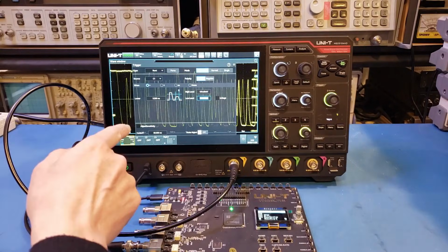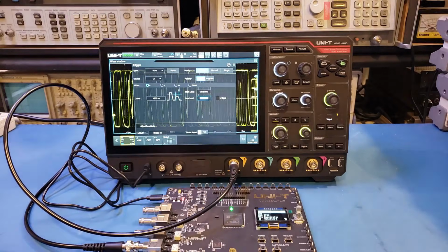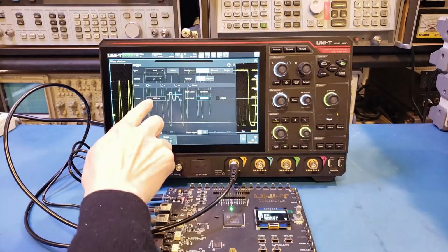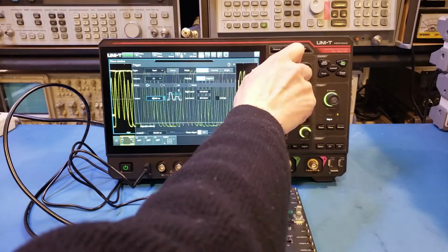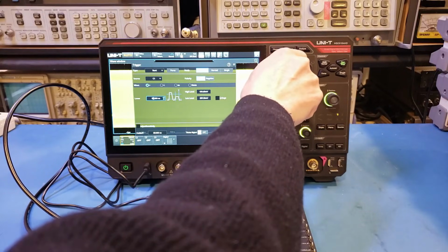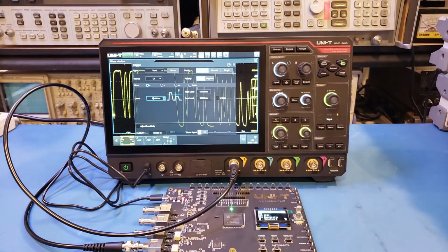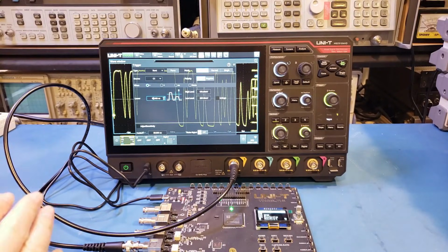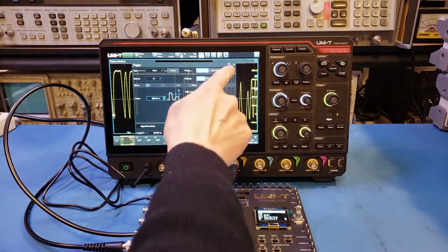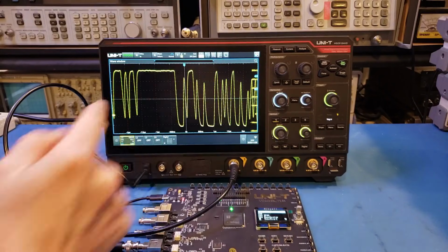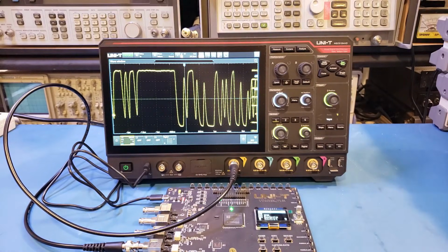Now we have the interval, and you can see here roughly per division is about 500 nanoseconds. So let's actually increase that. And you notice that at some point here, we actually are able to trigger it stably. So let's actually go back and take a look at the trigger signal. Of course, that's just a demonstration, and now you know how to trigger on the round pulse.